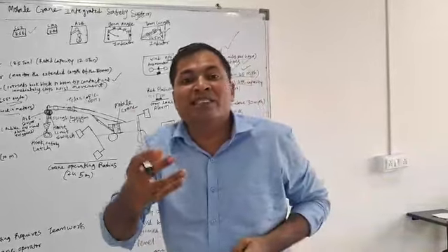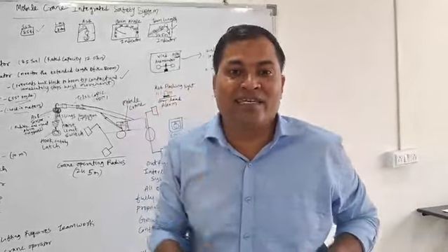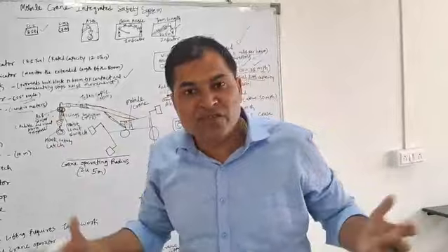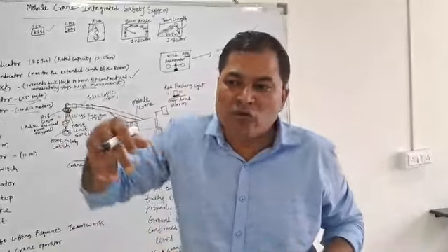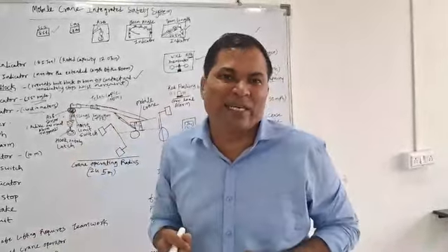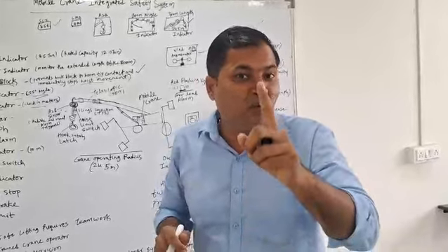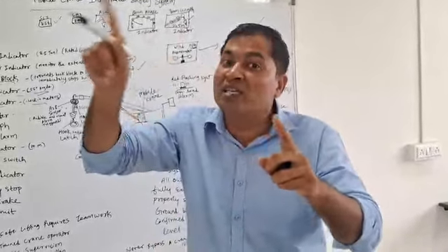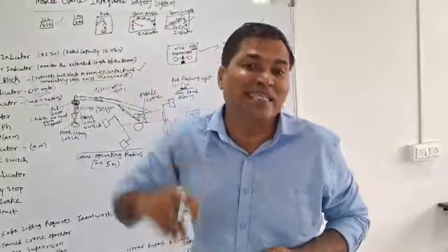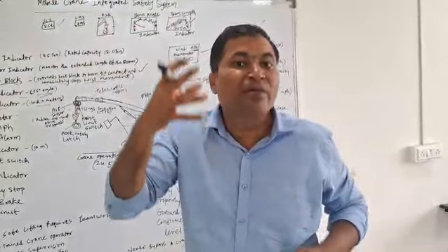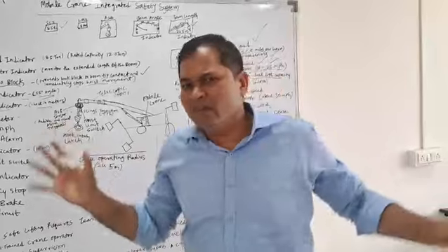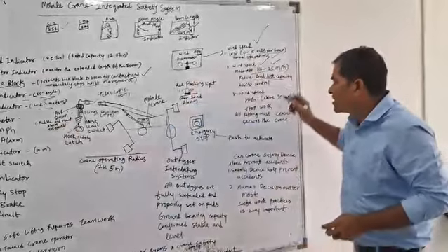means there are chances of an incident or accident. Your crane may collapse because of the wind. So always you have to reduce the load lifting capacity. Understood? Reducing the load lifting capacity is very important, because it also depends upon the climatic condition. Maybe thunder, maybe storm, maybe lightning, maybe wind speed as well. So these are the things which are very important.